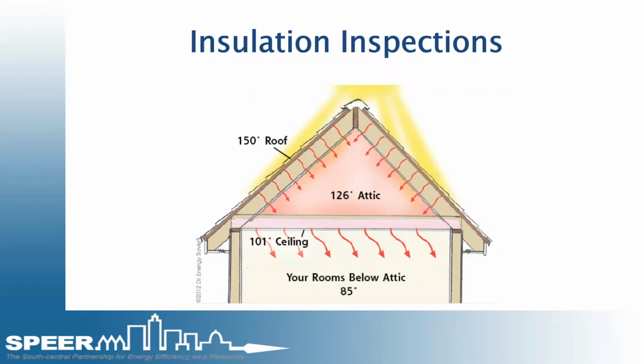in the attic is another reason why we have such high depths of insulation in the attic. You can't really cap it, and no one's really going to want to put a cap on it. So basically, the deeper it goes, the more depth of insulation, the longer it has to travel, the less likely it is that that heat's going to hit the sheetrock at a high temperature to then re-radiate into the house itself. So that's the only component really that's not trapped in a 6-sided encapsulation, but then they've doubled or even tripled the depth of that to overcome the fact of it not being trapped.